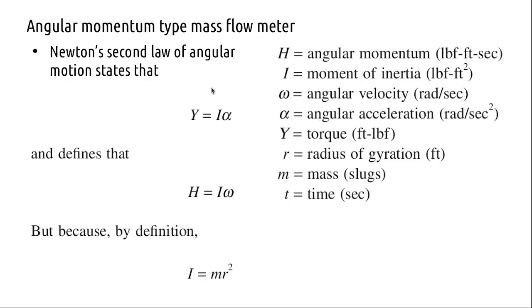This is a recollection from what we discussed last day. It is based on the angular momentum. So you are imparting a momentum to the fluid, and this fluid is going to strike some other rotating component, and the momentum will be proportional to its flow. So it will be imparting a torque to this other mechanical component, right? And the torque will be proportional to the flow. That is the basic idea.